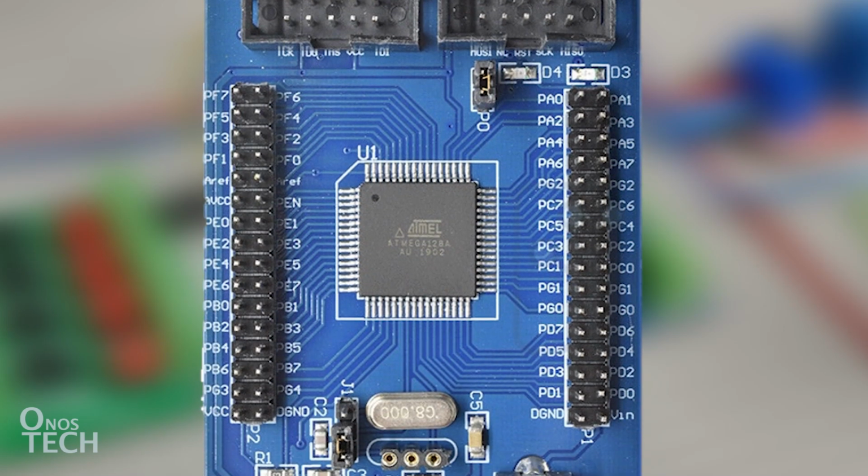The microcontroller port pins are extended to two 16 pins dual male header on both sides of the board. The 16 inputs of the Outseal PLC Mega are mapped to the Atmega128 development board pins as follows. S.1 to S.4 are the Atmega128 microcontroller pins of PF7, PF6, PF5, and PF4 respectively. S.5 to PD5 and S.6 to PE4.